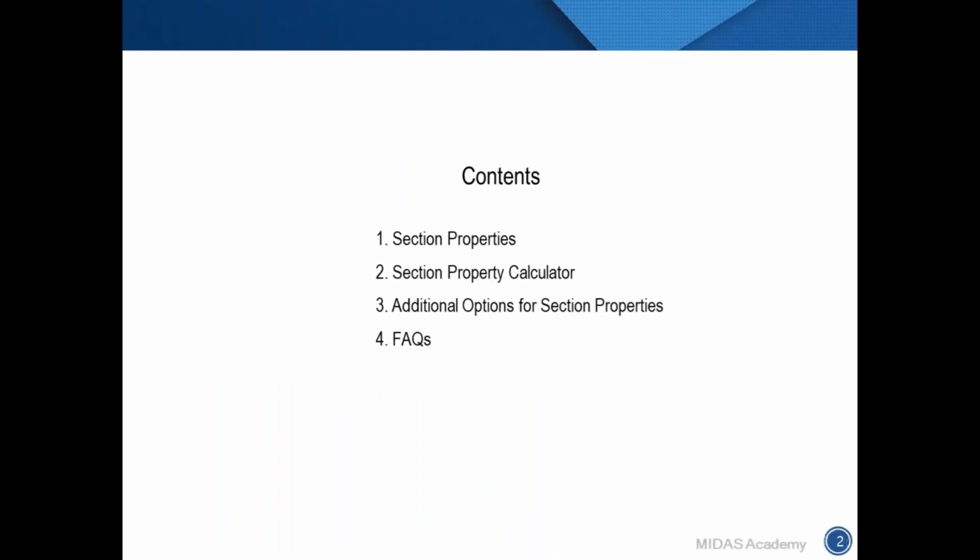Okay, so here is today's content. The first one, we will look into section properties of Midas Civil. After that, there is an additional function to make the user-defined section. We call it the Section Property Calculator, short form SPC.